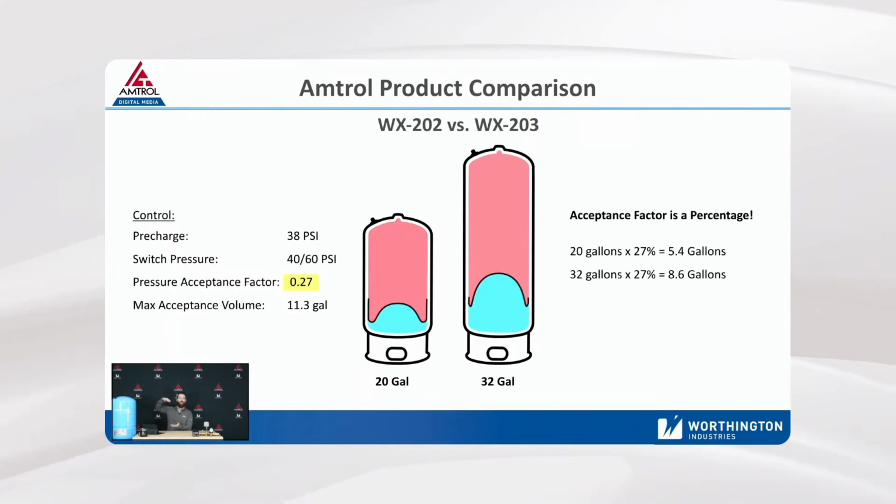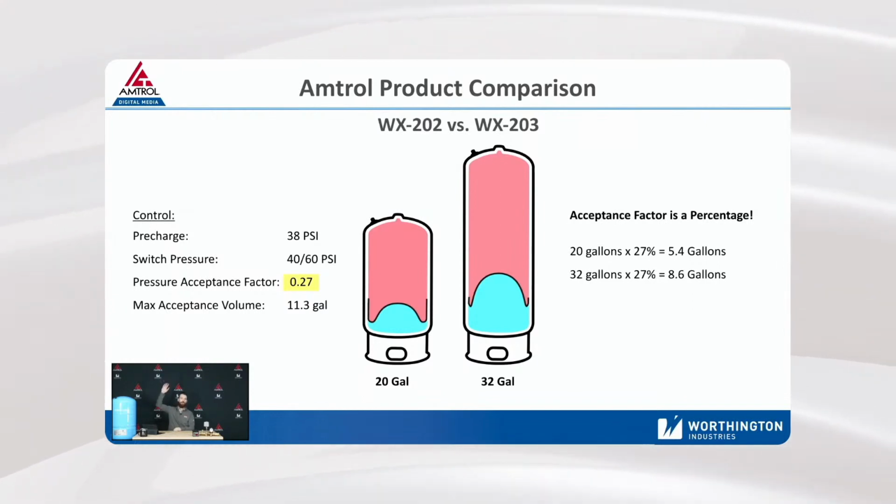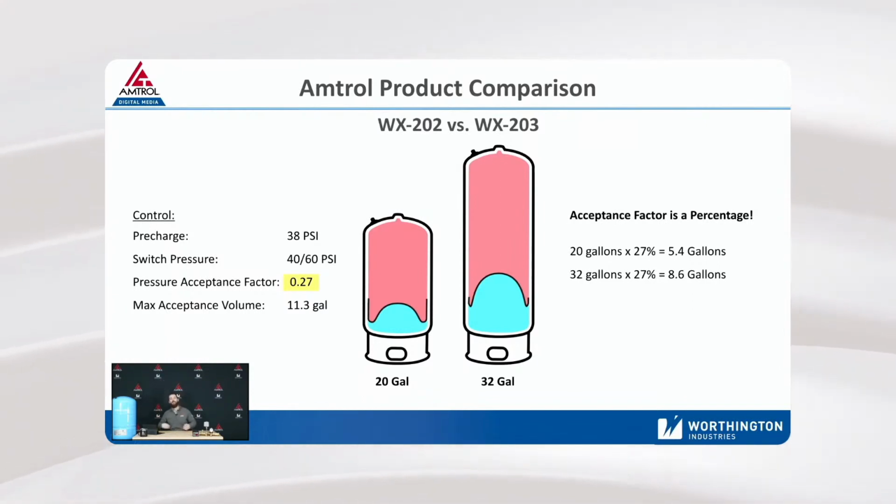That air volume is very important. So the more air we build, I mean, we could build this tank to the moon if we wanted to. Obviously, you couldn't move it. But with all that air volume, it could have the same water dome, and that diaphragm is going to stretch way more because you have that extra air volume. Obviously, there's a limit to that. That's why our tanks aren't 10 feet tall.